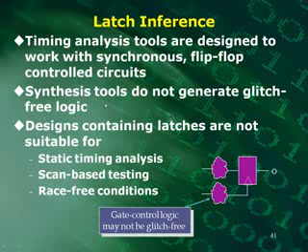And synthesis tools do not generate glitch-free logic. That's going to be up to you to realize what you're doing. Okay, what do I mean by glitch-free logic? Well, let's say that I had a flip-flop, and for the clock, it didn't just come from a particular clock source, but it came from some combinational of maybe a couple sources. Okay, you can get into a real problem here, and this is what's called a gated clock.